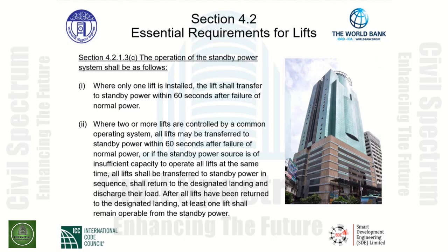This section gives us very specific limitations for buildings with one lift or buildings with multiple lifts, and the associated time limitation that the standby power must be supplied to the system on a normal power failure.